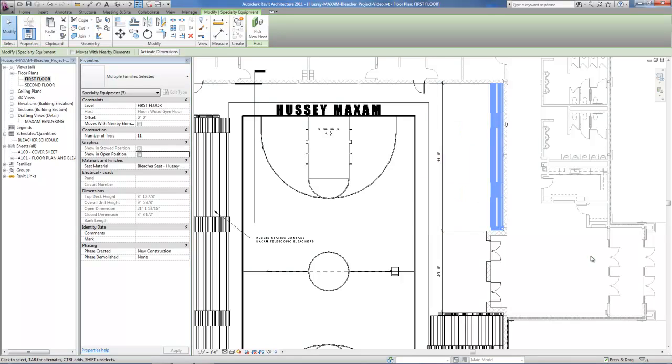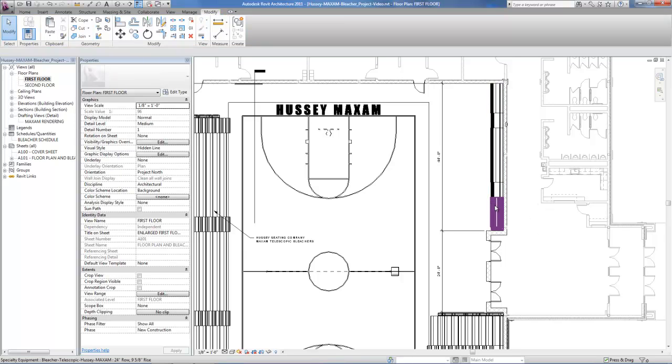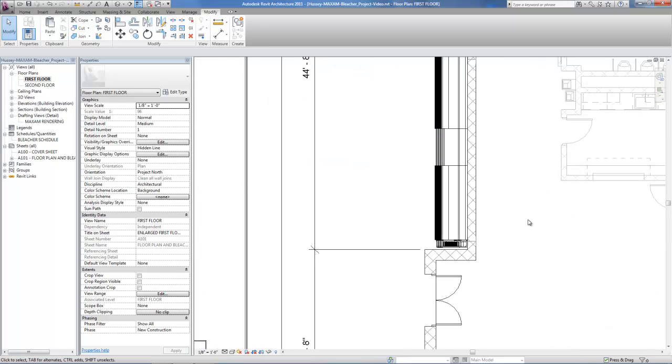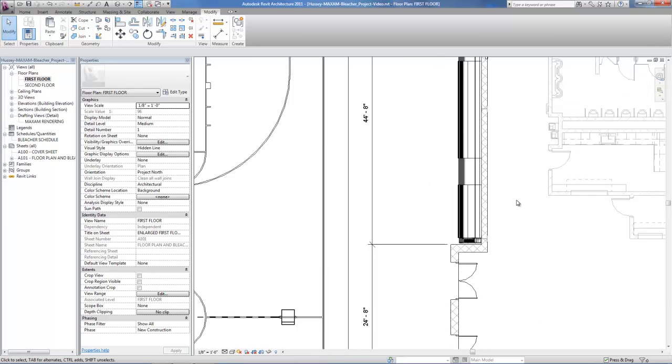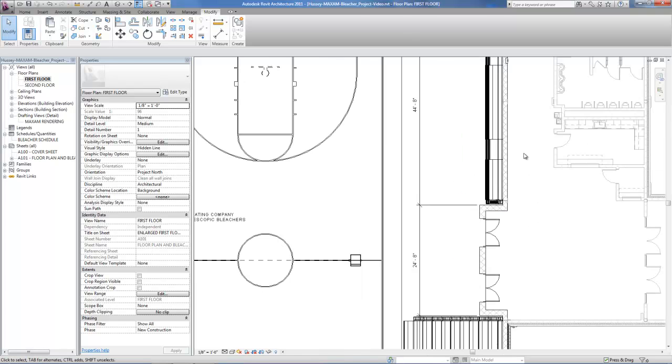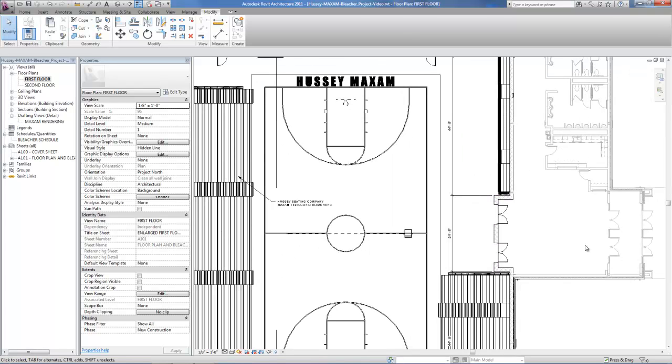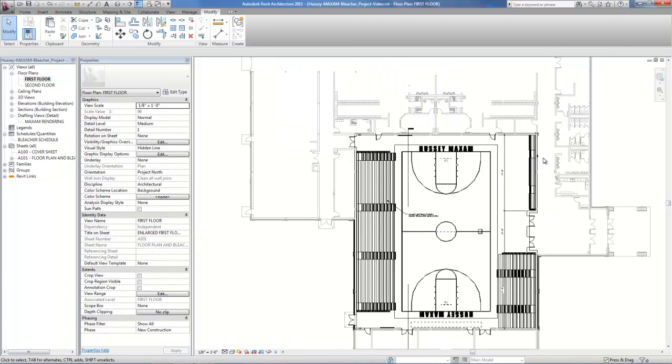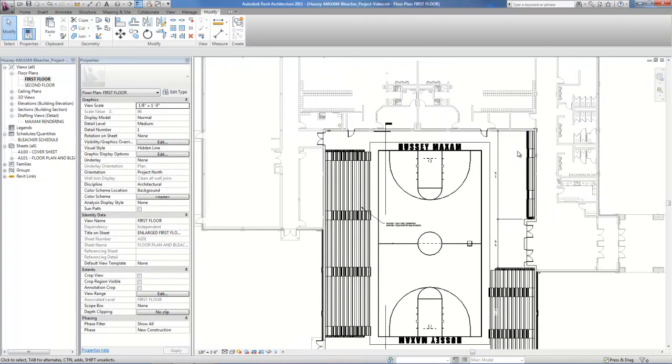The dimensions have been coordinated with the specifications, so no matter what your row spacing is, whether it's 22, 23, 24 inch spacing or 26 inch spacing, the open and closed dimensions will always be true to the specifications. The architect can now verify based on that he has a clean corner here and he's in good shape. He doesn't need to relocate this wall to satisfy that. And as you can see, that is an instance-based property, which means that all of these ones can be closed and all of these ones can be open, even though they're the same components.